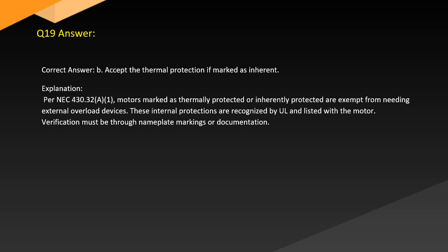Answer. Correct answer: B. Accept the thermal protection if marked as inherent. Explanation. Per NEC 430.32(A)(1), motors marked as thermally protected or inherently protected are exempt from needing external overload devices. These internal protections are recognized and listed with the motor. Verification must be through nameplate markings or documentation.